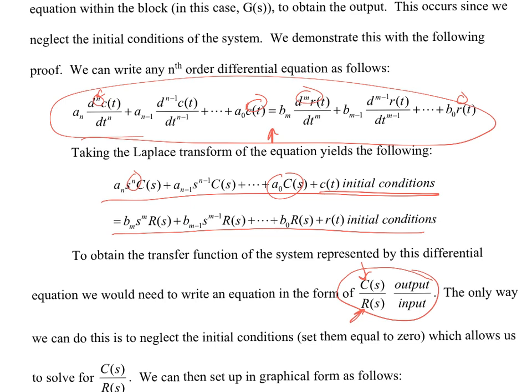If we want to do a transfer function, here's the key thing. We can't form this equation with a bunch of initial conditions. So all these initial conditions can't be included, which means to do transfer function approaches, you have to assume that your system has no initial conditions, which is not always a big problem, because remember back from chapter 6, we would always do a 0 plus to infinity. So we would add on whatever, let's say, c initial conditions are.